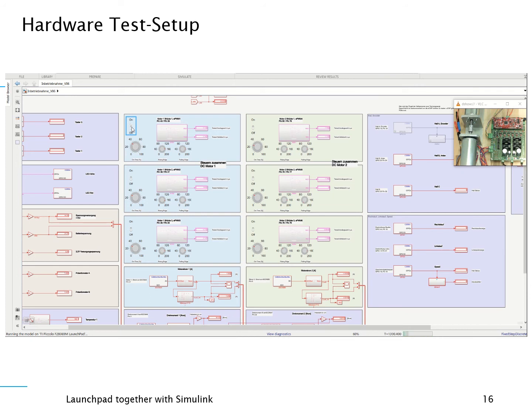I can change the direction of the motor if I now turn the other high side MOSFET on, or use the PWM cycle for this upper MOSFET. This is our motor 1. The same I can of course do for motor 2, and again in the other direction.